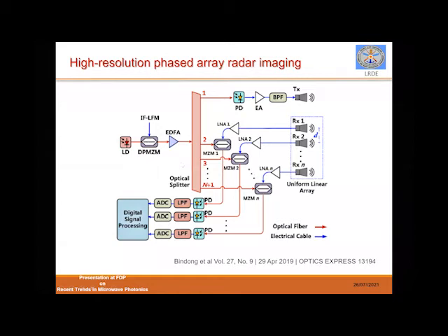So if I use the quadrupling method, it is called dual parallel MZMs, which basically configure the MZMs at different bias points to operate either for the quadruple signal, or we can get different combination outputs. In the case of quadrupling, you will get 4 times. So your center frequency will now become 8 gigahertz and your bandwidth becomes 2 gigahertz. Now, if you want to use it for timing, you may have to assume that you are getting a signal which has a very high bandwidth.